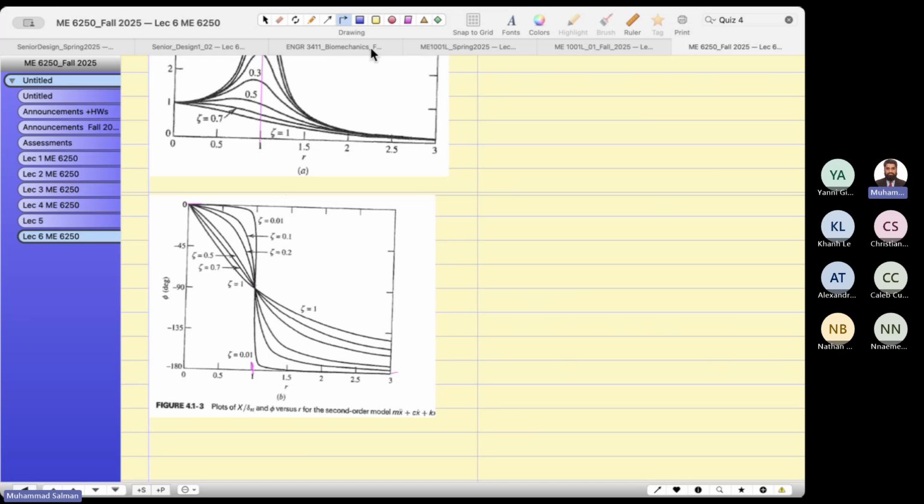Let me show you the physical meaning of this mass. Suppose this mass is moving up. It is following the phase at low frequency, but at high frequency the phase difference becomes negative. That's what it means physically. So you apply force downward, but at high frequency the mass moves upward. So they are opposite, by a 180-degree phase difference.